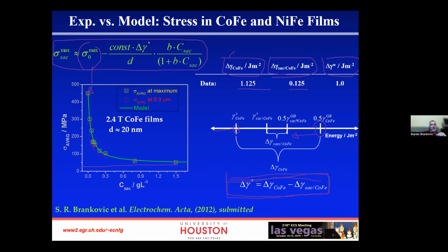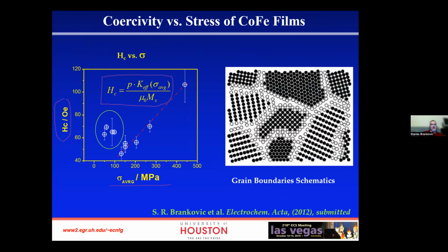adsorption. Okay. At the same time, as we discussed last time, the presence of the additive decreases the surface energy of the film because those dangling bonds that are high energy are saturated by the presence of the foreign molecules of the organic phase adsorbed on the surface. So that's this dual effect that results in the reduction of the driving force for the grain zipping process.